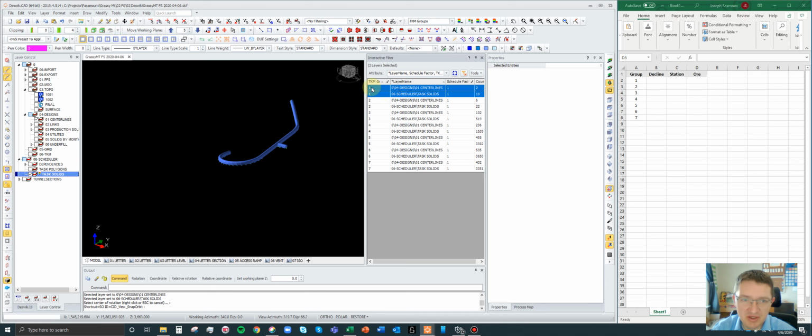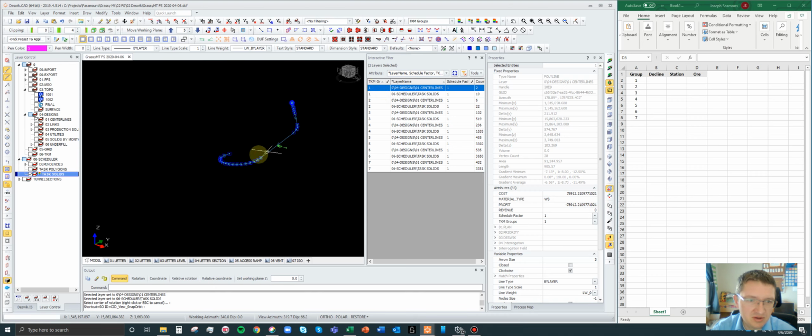Because now we can just be like, okay, group 1, click on this line. That's my distance. My length right here, 905.57. I wonder if I could copy that. Control C, copy. Control V. Boom. Don't even have to type it in. There's the length.